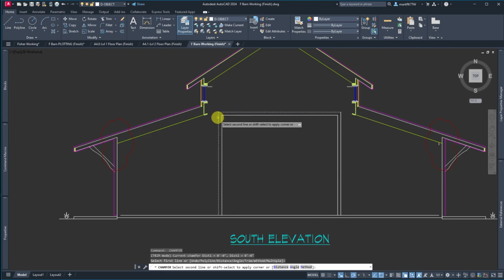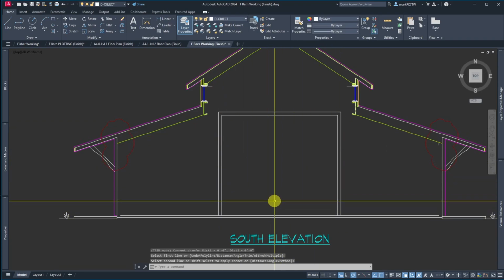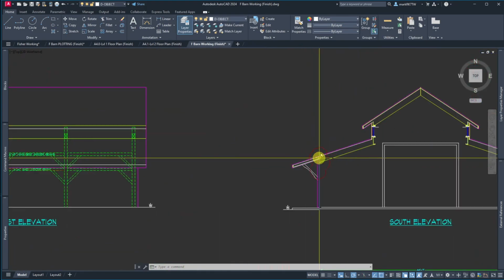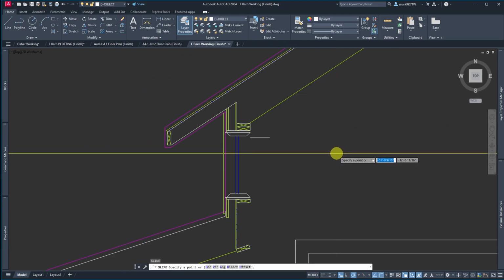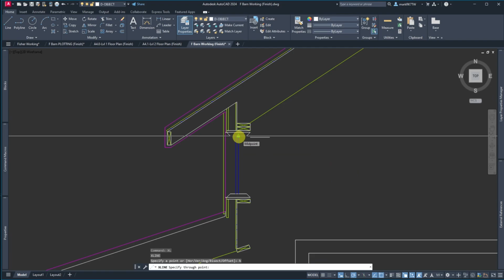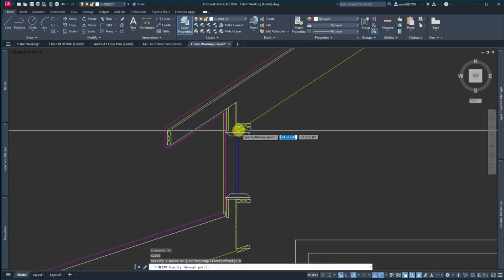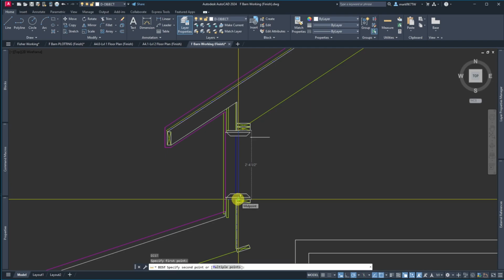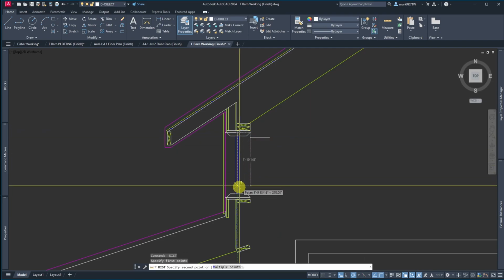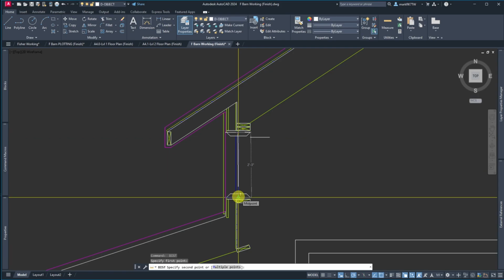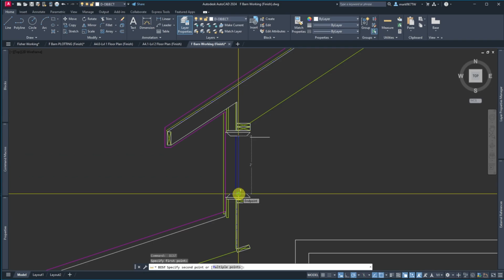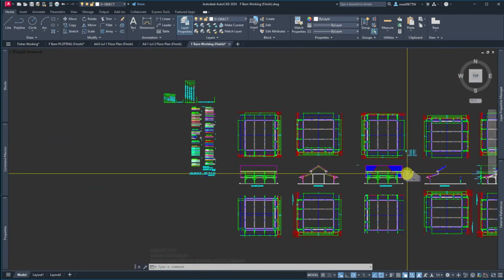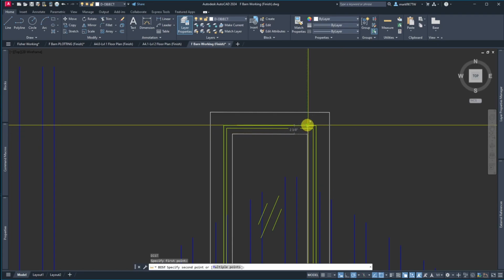And so then I could put in my roll-up lines. But what I'm after is, let's get these guys in here. So I'm going to do an X line, XL, H. And I'm going to show my glazing, my window, my frame. So let's check a distance here. Distance from there to there is 2'4.5". Let's try from here to here, 2'3". And I think my glazing, I could only get 2 feet. So those are 1.5 inches, 2 foot of glazing, and I don't think that's the way that this is drawn. Is that 1.5 inches? It's 2 1/4.